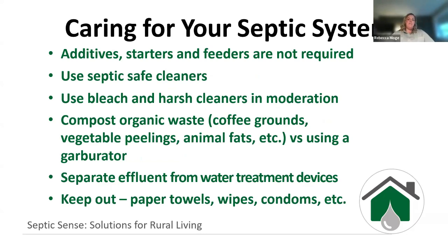Additives and starters and feeders are not required. We used to hear all the time to throw a dead chicken in the tank, and that's the starter that you need to get everything going, but that's not actually the case, not recommended. All the bacteria that we need to start providing treatment is in the sewage itself. So we don't need additives and starters. That is the effluent itself and the sewage that we're dealing with.